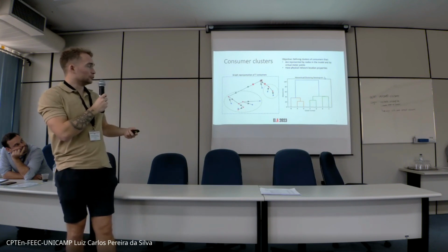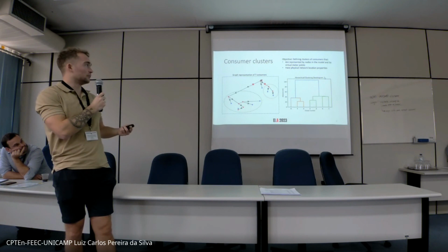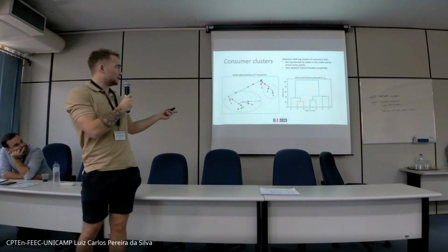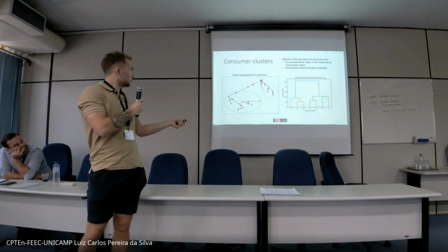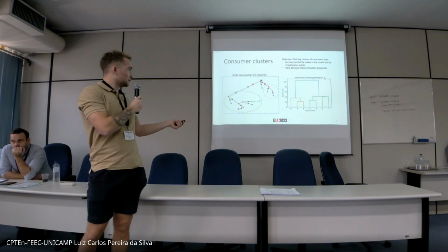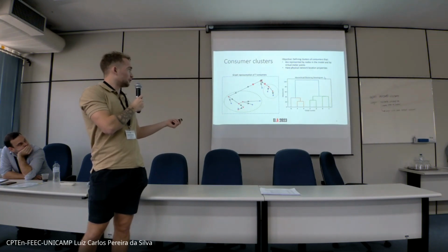The clustering approach we use is an agglomerative clustering approach, a bottom-up approach, you can say. We make a small modification to discard clusters which are not represented by a virtual meter point. And that's why we see that consumers 4 and 5, these consumers, are clustered together, but the cluster that contains or could have contained consumers 4, 5, and 6, we discard as a cluster because we don't have a virtual meter point which aggregates information of only these 3 consumers. So we can't use it for our comparison.